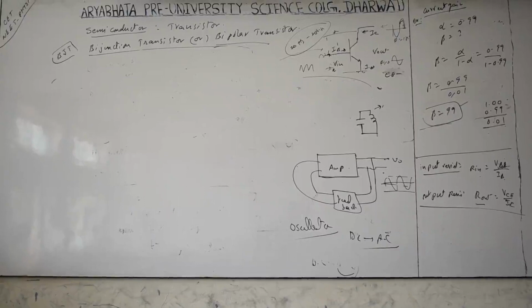By mutual inductance you can take the high frequencies; the core is not used. A ferromagnetic core is not used for high frequencies. For low frequencies, a ferromagnetic core is used. These two lines indicate the laminated ferromagnetic core. This is like a small transformer. Then a coil is taken like this, and one more coil is taken near this. This is going to be the feedback.